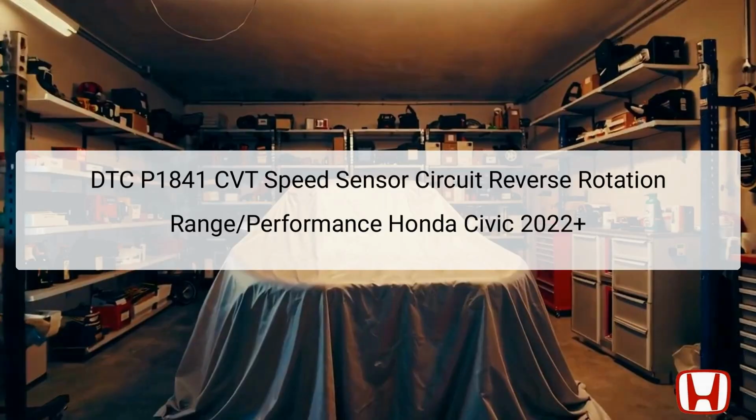The diagnostic trouble code DTC P1841 for the Honda Civic 2022 Plus specifically concerns the CVT, continuously variable transmission, speed sensors performance regarding reverse rotation. This error indicates that there is a discrepancy between the expected voltage levels from the CVT speed sensor signals and the actual driving conditions. When these signals do not align with expectations, the TCM, Transmission Control Module, interprets this mismatch as an anomaly and subsequently stores the DTC.